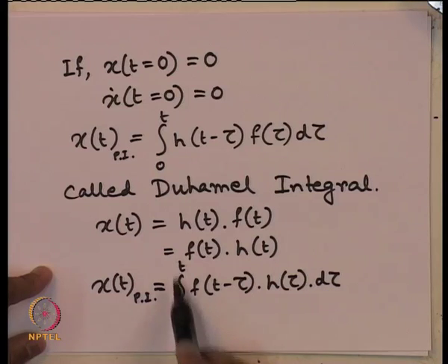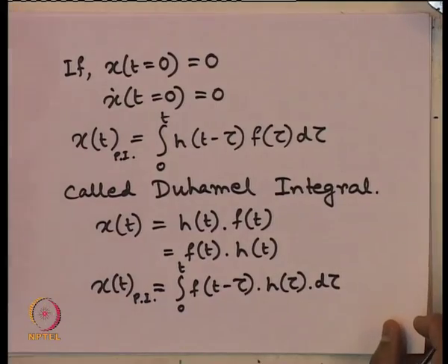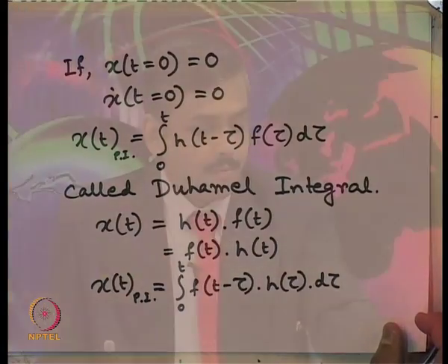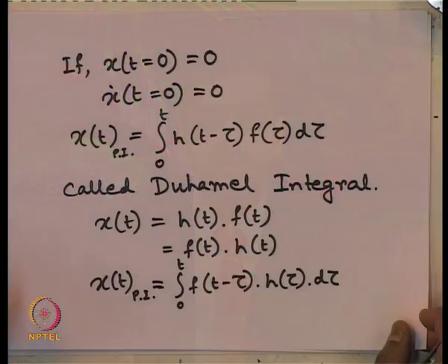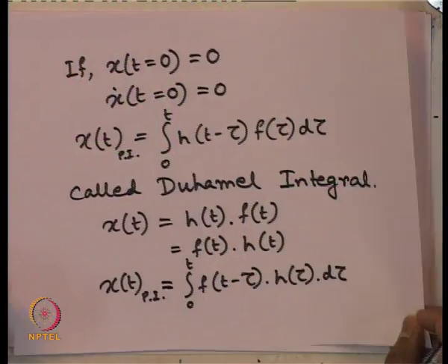With this you can integrate over the time t varying from 0 to t. In that way the complete solution for any system subjected to arbitrary dynamic load can be obtained using the concept of Duhamel integral if it starts from absolute rest.